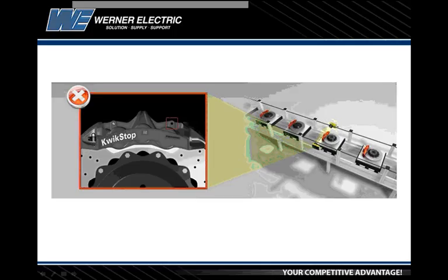The bottom line is the camera can search through the image and locate the part first, and then follow that up with checking the presence or absence of various features on that assembly. So if these caliper housings move from part to part, then you can't use a photo eye anymore because you don't know where the feature you're supposed to be pointing at is. That's still an application that can be solved quite simply with machine vision.